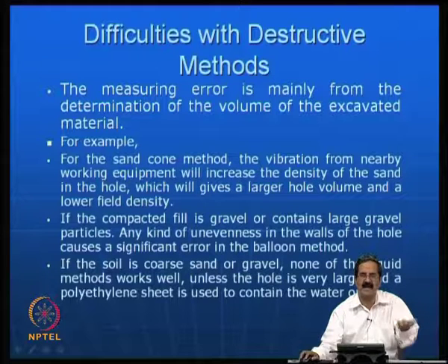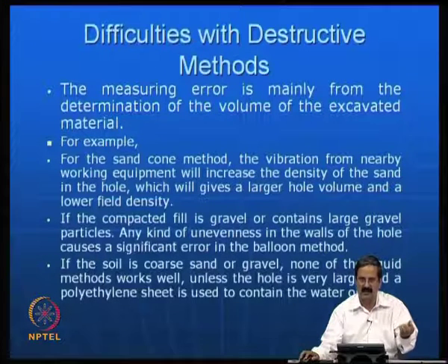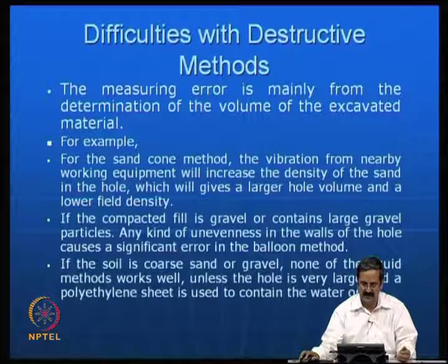You can use a sand replacement, you can do a liquid replacement, anything. Even a shrinkage limit test is nothing but a mercury displacement. You are trying to find out the shrinkage volume by using mercury displacement. So one should be very careful, particularly when dealing with materials like this. Okay.